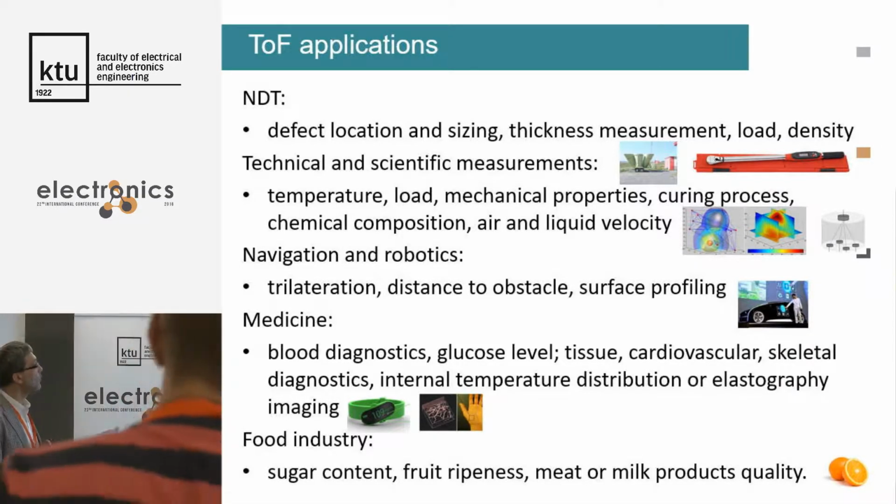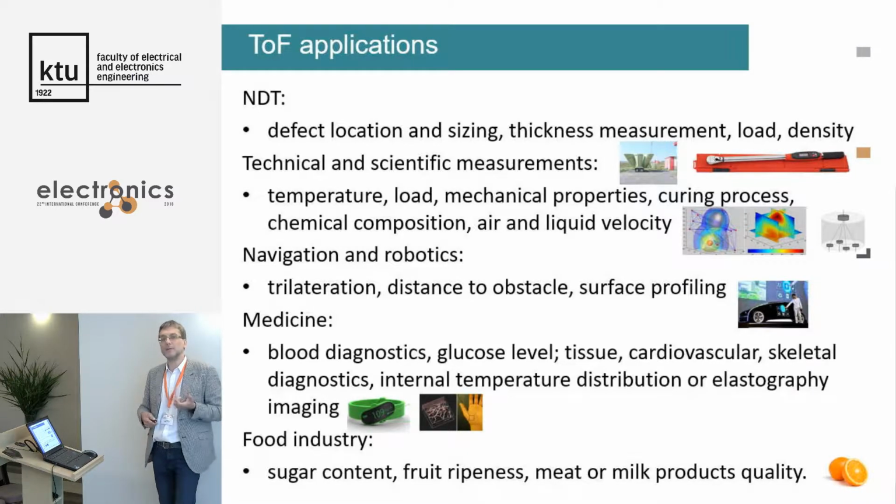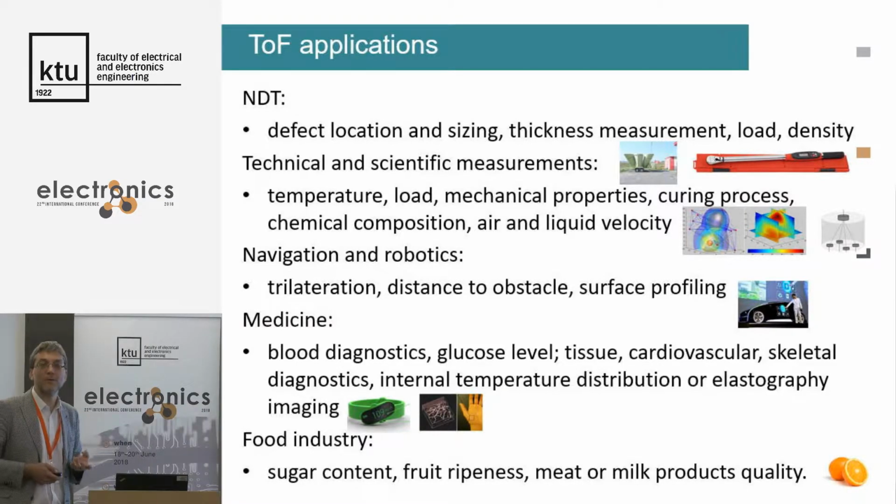And of course, in all scientific technical measurements, for instance, this is the sonar that is used for probing to get the distance to the clouds, not using radar technology, but ultrasound. Because the mechanical properties depend on temperature, ultrasound can also be used for non-invasive and very fast temperature measurement. For instance, if you use a usual sensor, it takes minutes for the temperature to settle down. Remember how long you have to keep the thermometer in your armpit. But with ultrasound, it is just immediate, and there are many applications like flame.